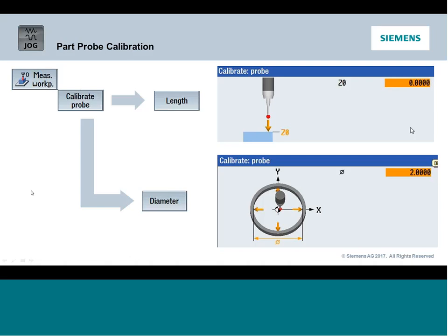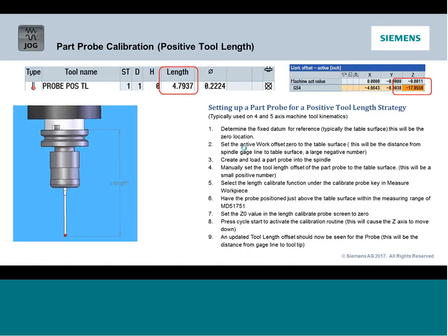Okay, so Rob asks, is there a way to get machine coordinates from probing results from within rotated coordinate systems? That goes directly back to the example I showed where we're using cycle 800. As long as you're using our dynamic fixture offset, which is really our 3+2 routine, our cycle 800 routine, then you can probe in any orientation, and it's going to take that dynamic rotation, a coordinate rotation, into account and give you the right result. So I think that's what Rob is referring to. If it's not, or if I missed any other questions here, because we got a bunch of them.